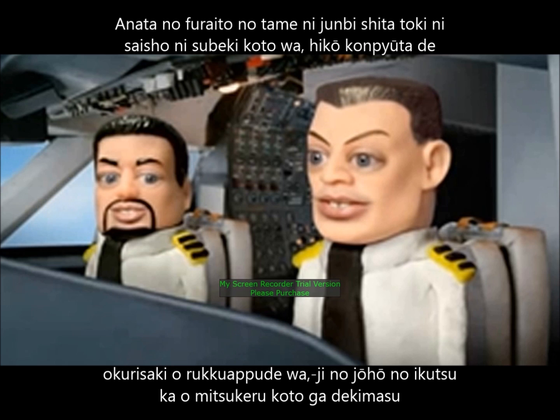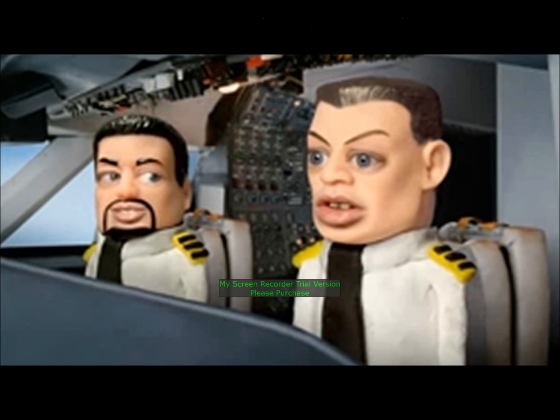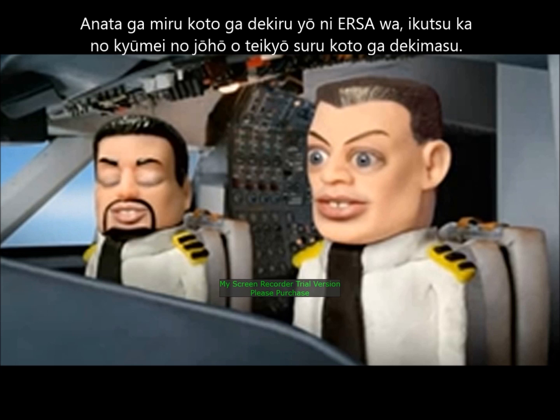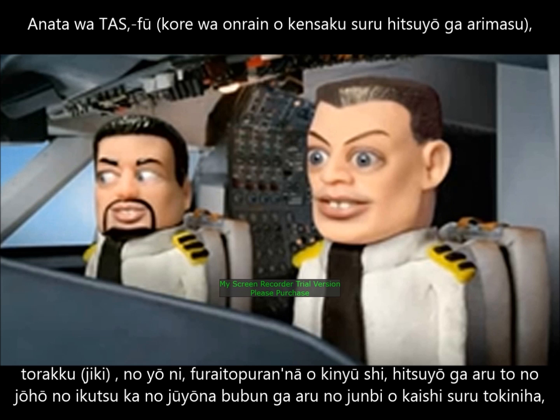When first preparing for your journey, the first thing you should do is look up your destination in an URSA. An URSA can give you some of the following information about your destination: aerodrome code, aerodrome obstacles, lighting of runway, elevation, what type of fuel they supply if they supply any at all, charts relative to the aerodrome, location, radio navigation, landing aids, local traffic regulations, passenger facilities, and they also supply additional information for certain aerodromes. So as you can see, the URSA can supply you with some life-saving information.